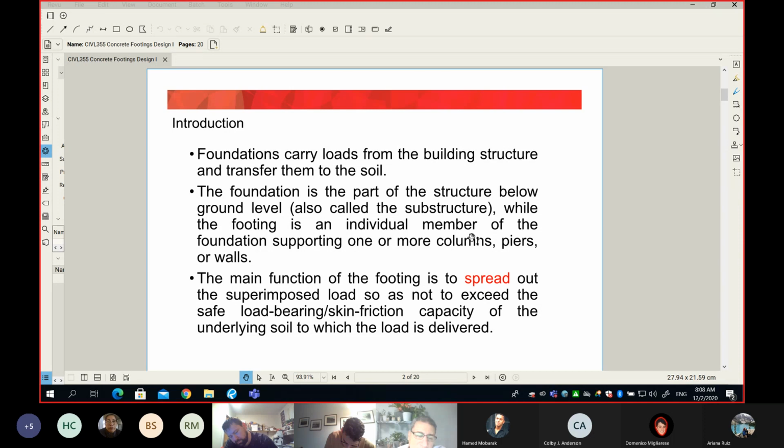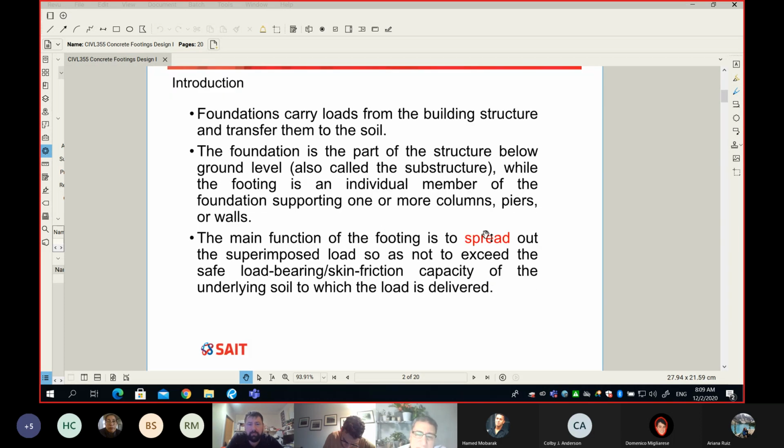Okay, if you chose not really the best foundation system, let's say you're supposed to go with piles, but you never did piles, and then you did just a shallow foundation, as we discussed today, your structure maybe will have significant settlement and significant deformation and lots of cracks, and probably the building will have to be demolished. Okay, if not collapse.